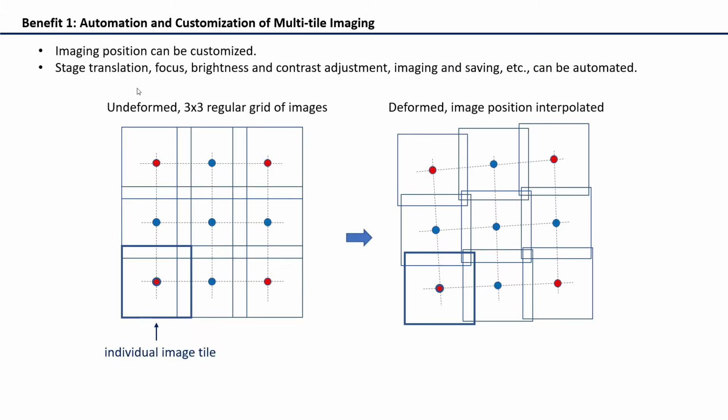The first benefit of using these scripts is that we can perform automated and customized multi-tile imaging to cover a large sample area of interest with many individual images that have a manageable image size and resolution. In fact, many of the SEM systems may already have a built-in function for this purpose, and sometimes they might even be a better solution. But having a customized script means that you might get some additional flexibility for this process.